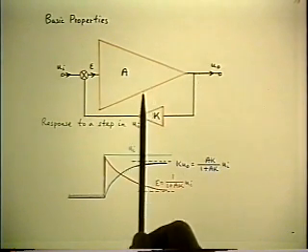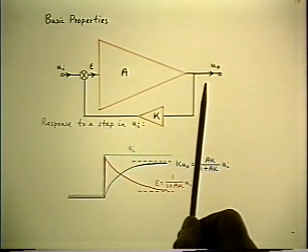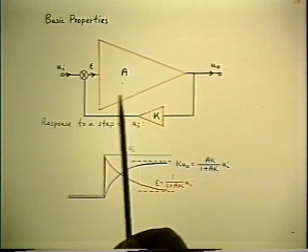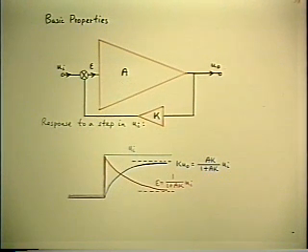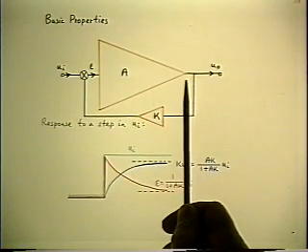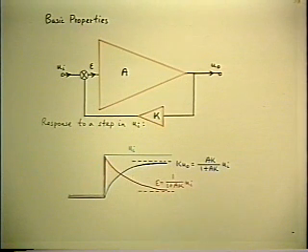Something saturates, shuts off, and the output clamps until the system recovers, which is determined by totally different parameters, such as slew rate, which is to do with what current sources and sinks are available to adjust the internal capacitances to the new values. The problem is totally different. It's no longer a linear circuit problem, with the consequence that these nice, neat, simple waveforms simply don't apply.